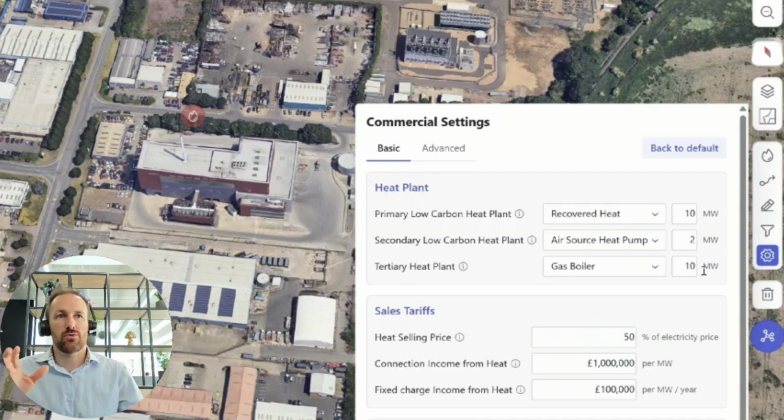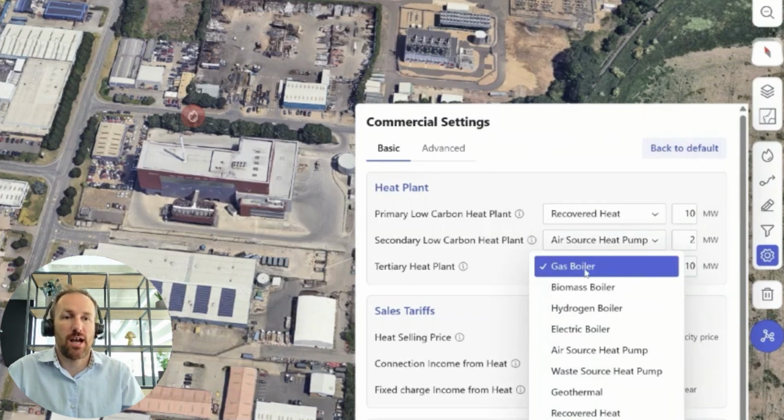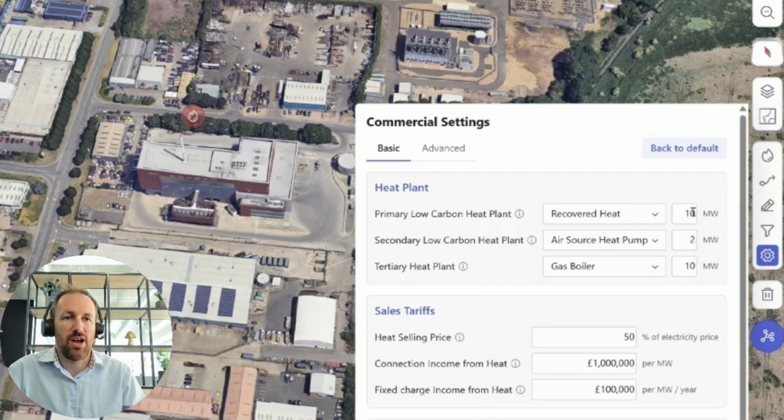The next phases, you've got iterative design processes to go through. So how big is your heat demand? How big is your heat supply? How do you make those match to a certain extent? You're nearly always going to have gas boilers as your tertiary, your backup emergency plant. So everything else fails, you've always got your gas boilers to run from. You're not planning to use them, or almost never. Maybe on a particularly cold day in winter, you chug those on because nothing else can cope. So they supplement the rest of it on really cold days. But other than that, you're not planning for them to run.